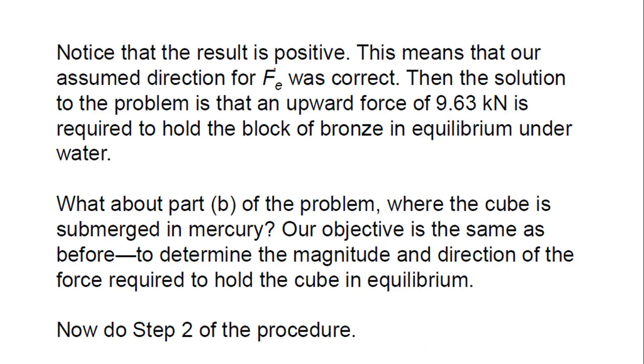Notice that the result is positive. This means that our assumed direction for Fe was correct. Then the solution to the problem is that an upward force of 9.63 kN is required to hold the block of bronze in equilibrium underwater.